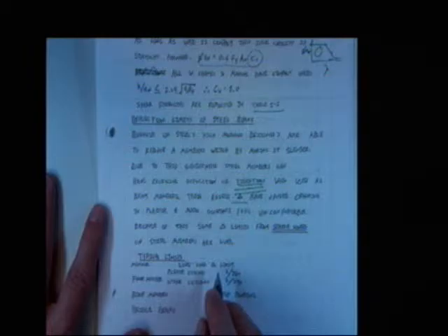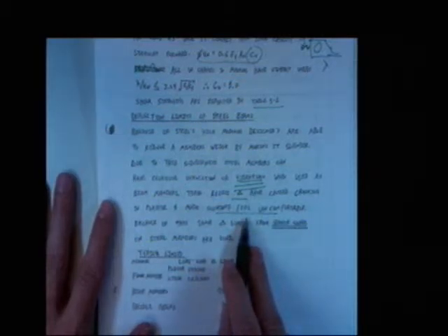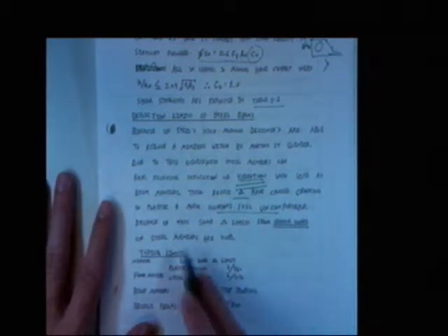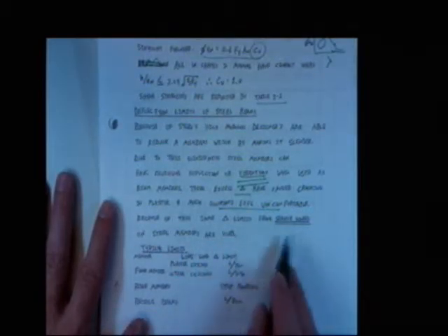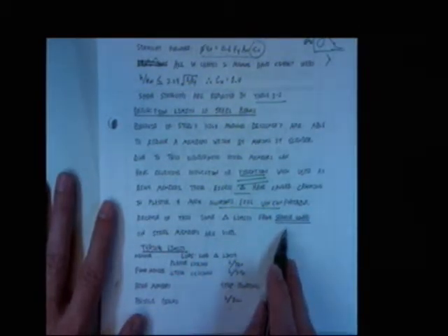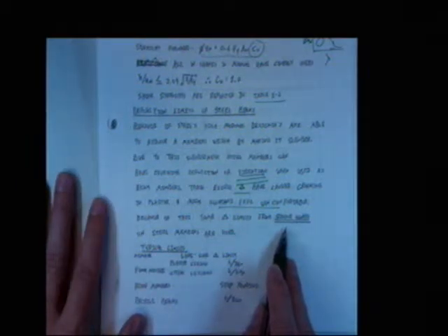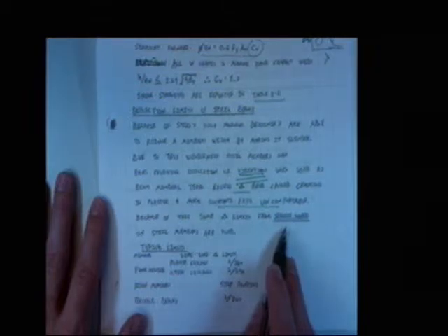Again, it's really important in this class to understand why just as much, if not more, than how. Okay? So excess deflections have caused cracking in plaster and made occupants feel uncomfortable. That's from vibrations. Okay? Because of this, some deflection limits from service loads, I've underlined service loads twice. What are service loads? What does that mean? It means live load. It doesn't mean dead load.